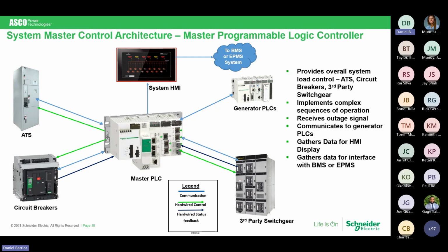If you need BACnet or one of those others, you need to specify that. More importantly, who is responsible for the translator between Modbus and your BACnet facility? Is that by the Johnson Controls people? Is that by Schneider? Who is responsible for that? That can be a very serious issue later on if nobody was held responsible for it.